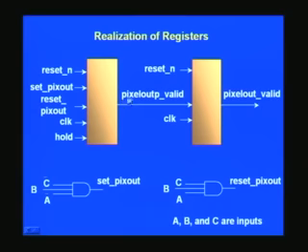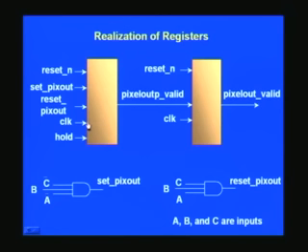So, here this pixel, when it is valid, pixel information is the image information. When it is valid is indicated here, and these are all basically the same signals what you have seen except for few differences. For example, you have used an asynchronous reset here and then a clock input. Once again it is positive logic we will confine our attention to, and then there is one more signal called hold, we will come to that, and set and reset are two new terms introduced in this. And what it does is, for example, this is just a register and we want to either set or reset. So, accordingly you have to make a condition.